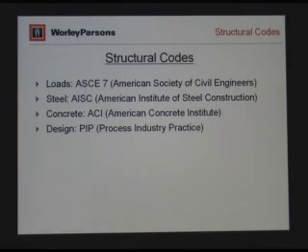So it's a different approach. Again, it's quite a change for us that have been using the allowable stress design. But again, I assume that probably, as in concrete, the next edition or the following revision will be just one approach, which again will be a strength design approach. Concrete, when I first started designing 30 years ago, we made the transition from allowable stress design to ultimate strength design. So this is pretty much common now.